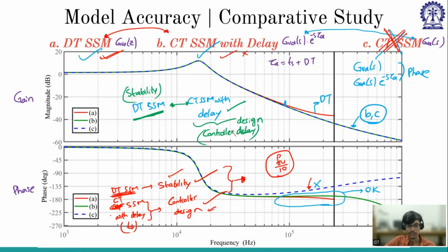Sir, for the discrete time model stability, we have to verify using eigenvalues. Yes, using the eigenvalues, that mod z something equal to 0. So you will find z values, and you have to ensure they are inside the unit circle. Then you can ensure the system is stable. Understood? Whoever is asking the question.